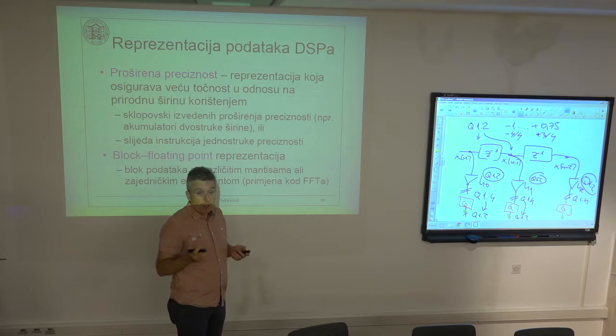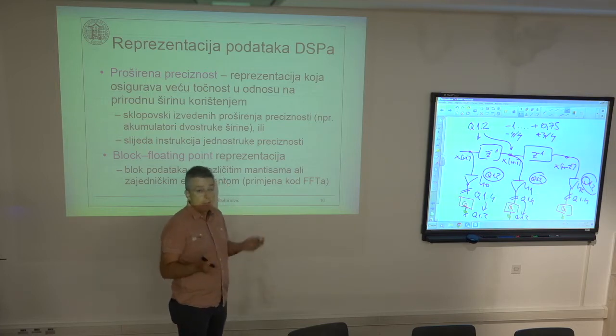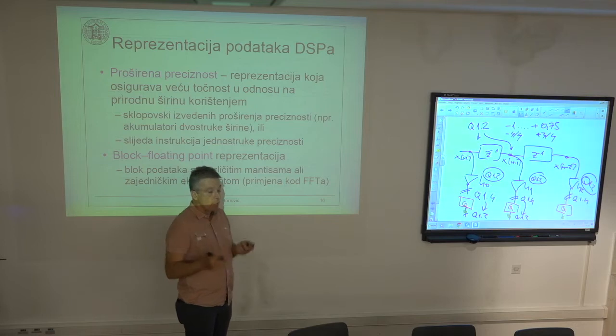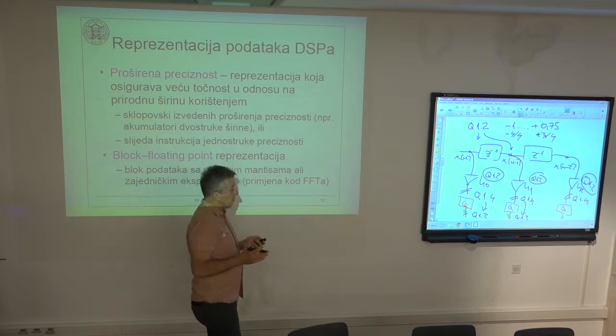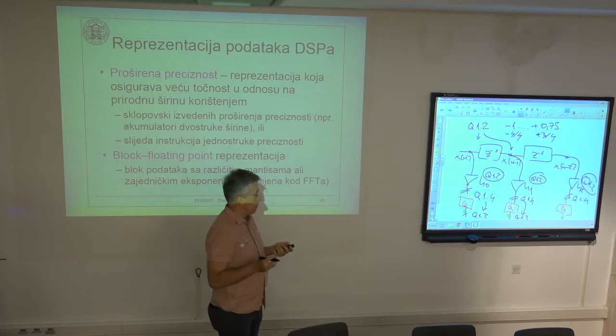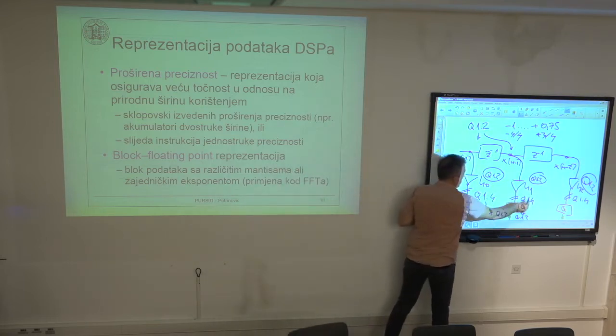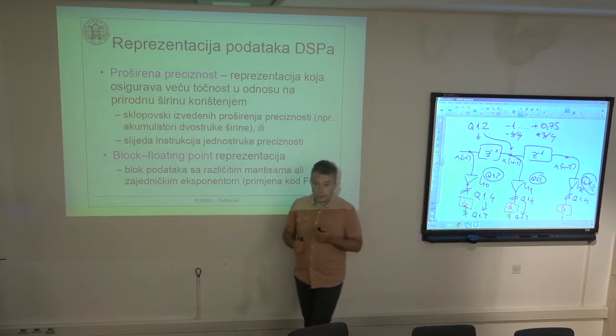Of course, the reasoning is, in this case, I have a single precision adder because the architecture is single word. My architecture is 16-bit, for example. I have a 16-bit adder. But the alternative would be to have a double-width adder. Why don't you use a double-width adder, and then first add up these double-width products together?